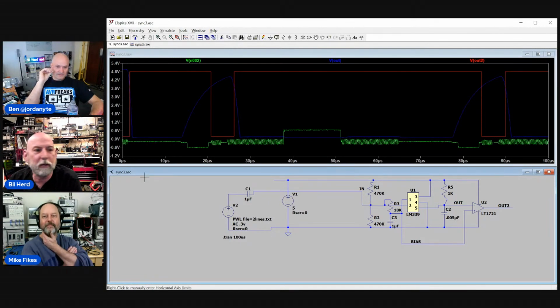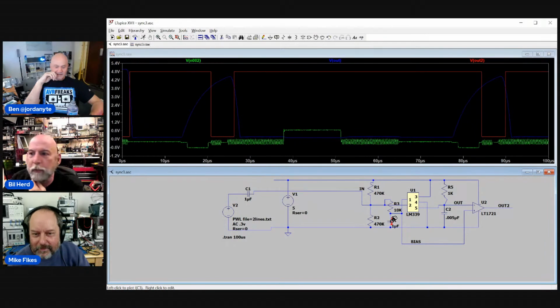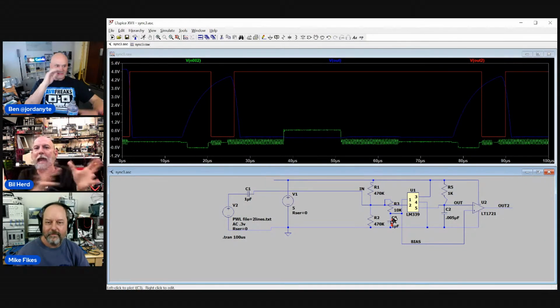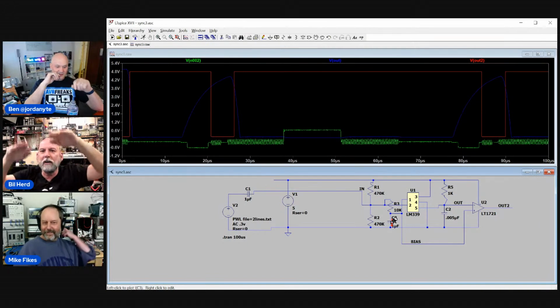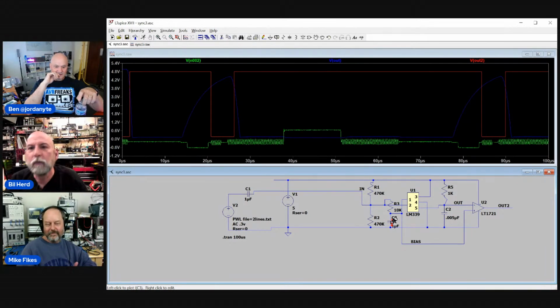There's something interesting in the circuit. Ben, if you look here, I've got a differentiated, or AC coupled, input, but I also have a filtered input. That's like the past. It's a delay and it's filtered, so it's an auto baseline. No matter what the baseline is, it'll track to it slowly. And then I find any quick pulses that come off of it relative to that slow tracking bias.